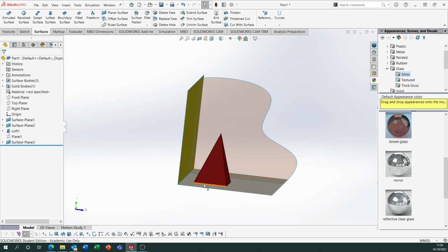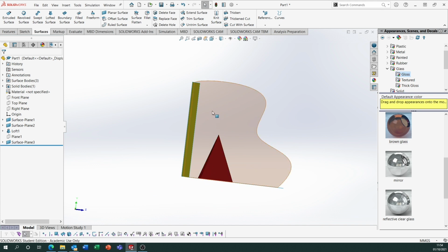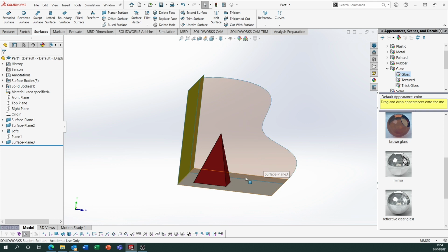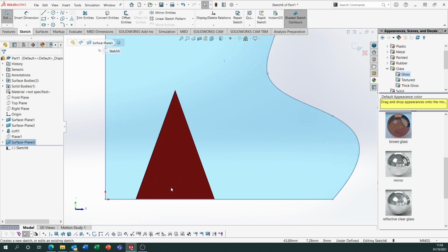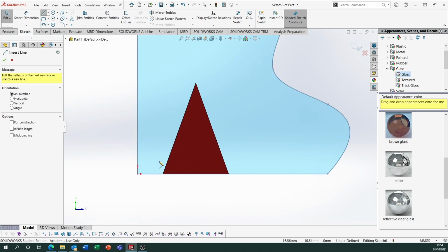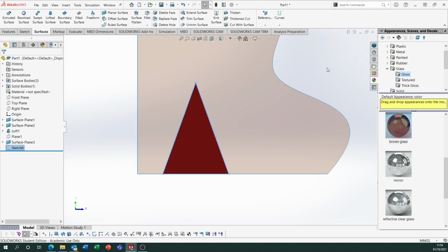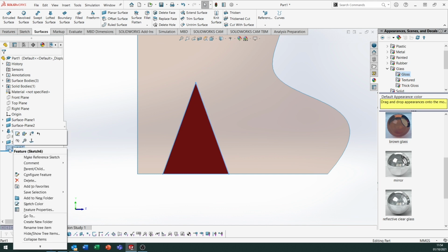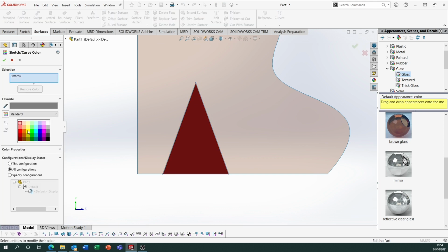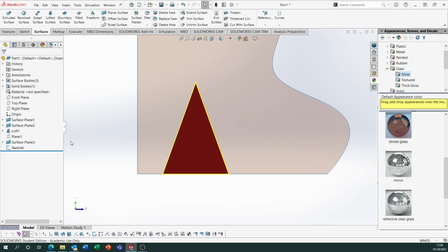So I'm going to project the outline of this onto our auxiliary plane, giving us an end view, and then in the end view, we're going to rotate that into its new position. So if I start a sketch on that auxiliary plane, trace the outline of the square-based or rectangular-based pyramid, and close that sketch. That sketch there is just the outline, and at this point I'm going to change the sketch color of that to something bright, so yellow.